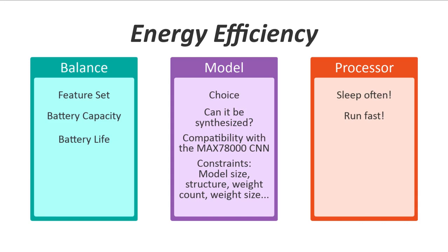Part of CPU clock minimization involves paying special attention to time spent dealing with I/O. This can often be the most inefficient part of the design. Reducing CPU involvement with I/O handling is often key, and you may want to take advantage of DMA-enabled peripherals as much as possible.